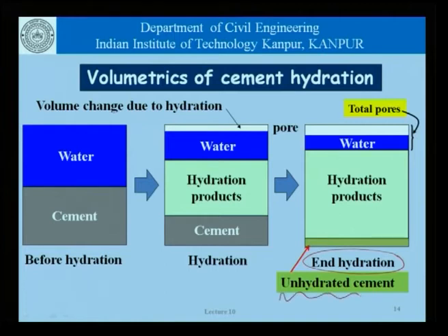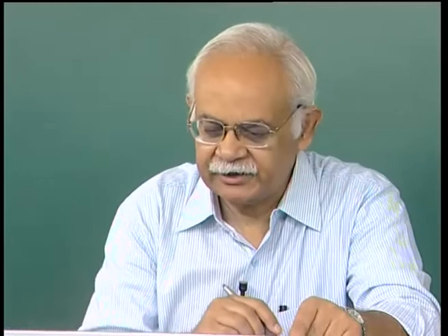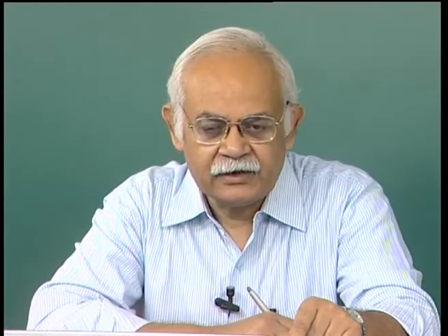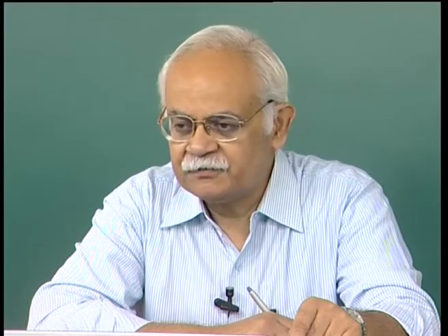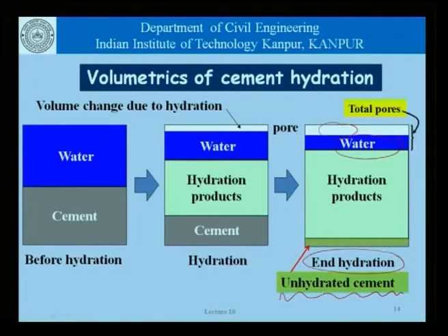There is some unhydrated cement still left here, but even in that case, some amount of excess water will be there, and some amount of pores which have been formed on account of shrinkage of the hydration products with respect to the volume of the reactants will still be there. So, nothing really changes as far as our understanding of the genesis or the origin of pores in cement paste is concerned.